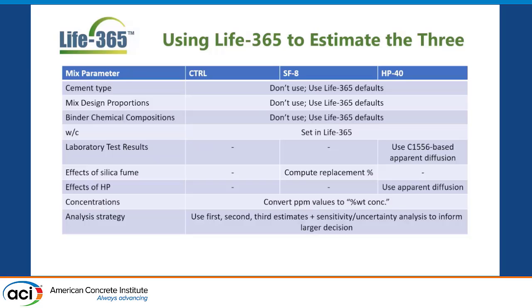Yeah, I think it's a relatively easy one. You spoke to varying element size and how that can change results by kind of the one-sided solution. Yep. About 12 years ago, I was reviewing a parameterized study using Life-365, and I zeroed in on the importance of discretization, and at that time, the discretization was fixed. So again, same cover, different element size, and kind of where that near-surface discretization landed relative to bar depth. And I don't remember if I was talking to Evan or whoever the programmer was at the time, but it was like 10 or 15 fixed discretizations regardless of element thickness.